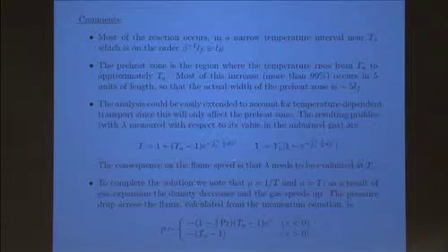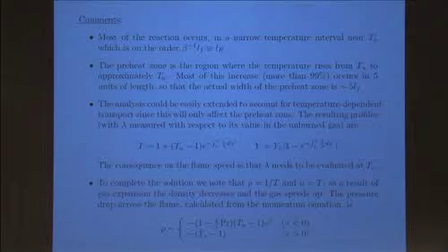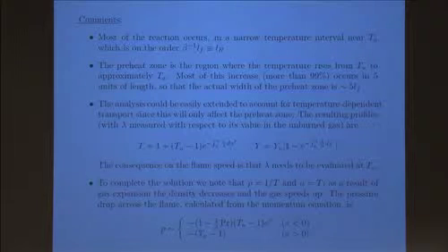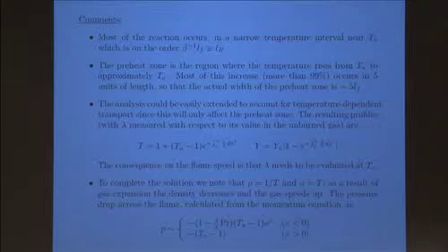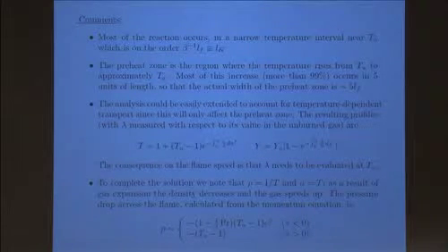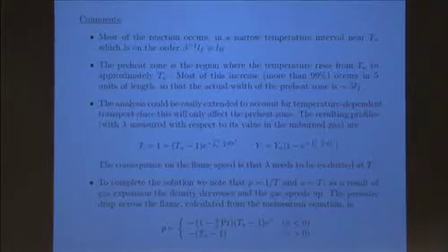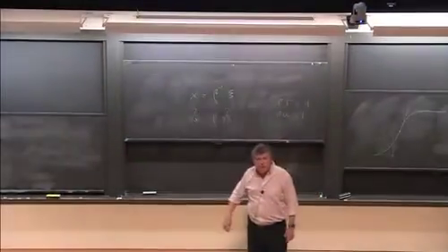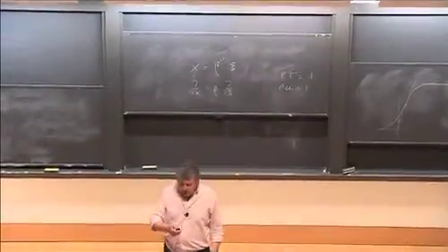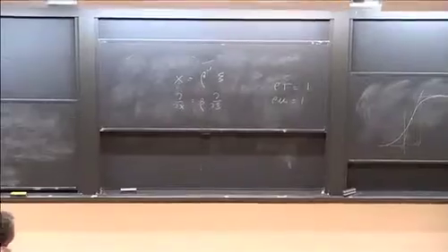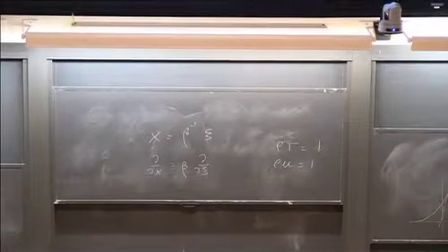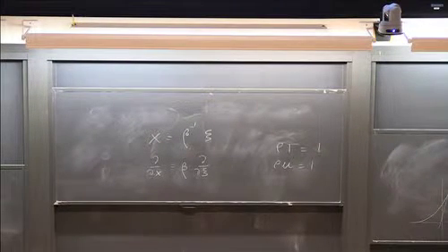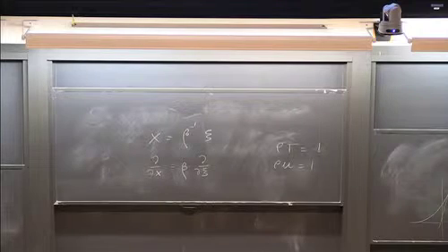Now, we have solved for T and Y, but of course, we have two other relations from which we can compute the rest of the solution. For example, from the equation of state, rho T equal to 1, we can compute rho, right? Which is going to be 1 over T. And from the continuity equation, rho u, we can compute u. So u is going to be proportional to T, and rho will be inversely proportional to T. In other words, as a result of gas expansion, the density decreases, and as a result of that, the gas speeds up, okay?